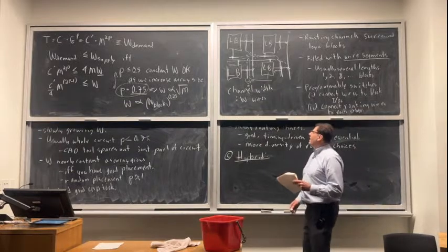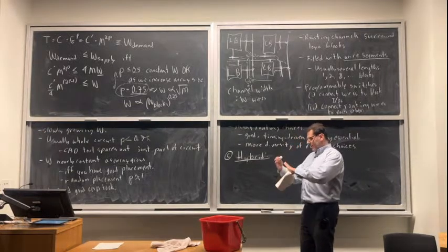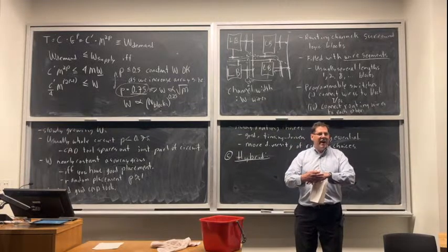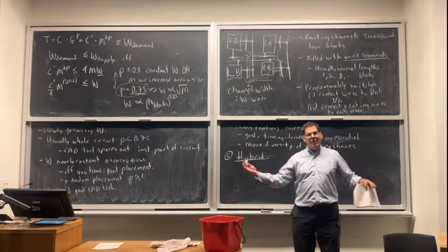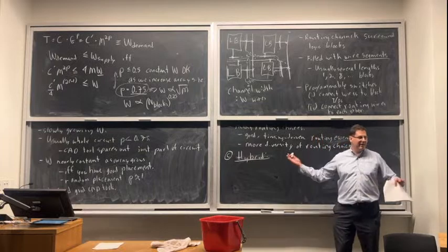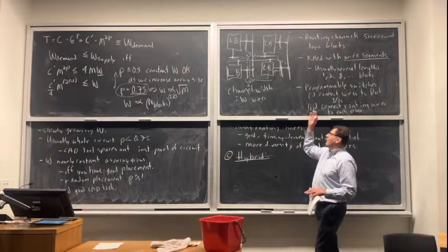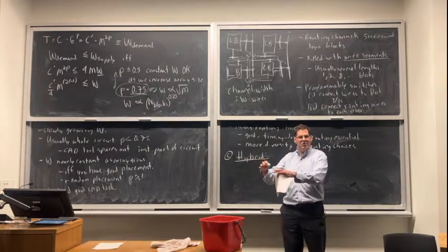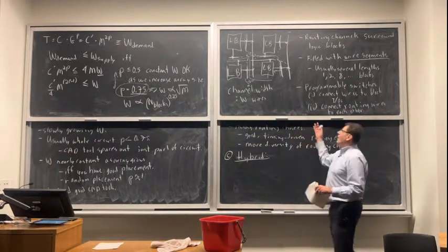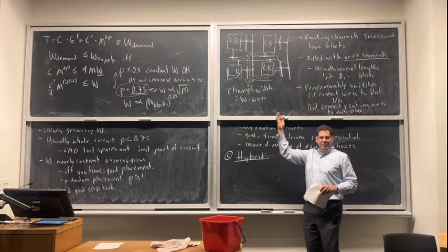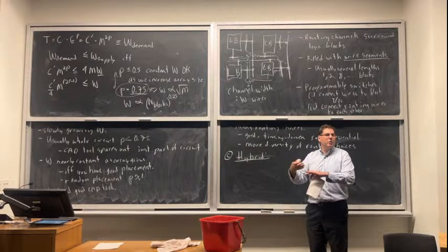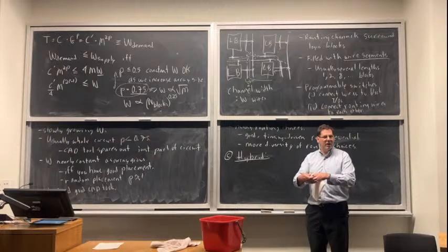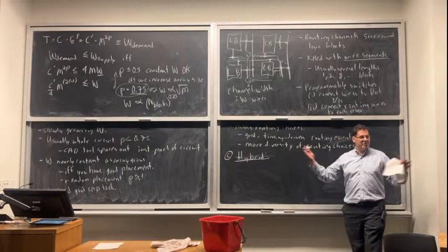One way is we could make little island-style FPGAs, and those are going to be our new logic blocks. Then we connect those logic blocks together with hierarchical routing to make the whole FPGA. Little island-style FPGAs stuck into hierarchical routing. Or we could do the opposite. We could make little hierarchical FPGAs, replacing individual lookup tables with simple hierarchical FPGAs that we call our new logic block, and then connect those together with island-style routing to make the whole FPGA.